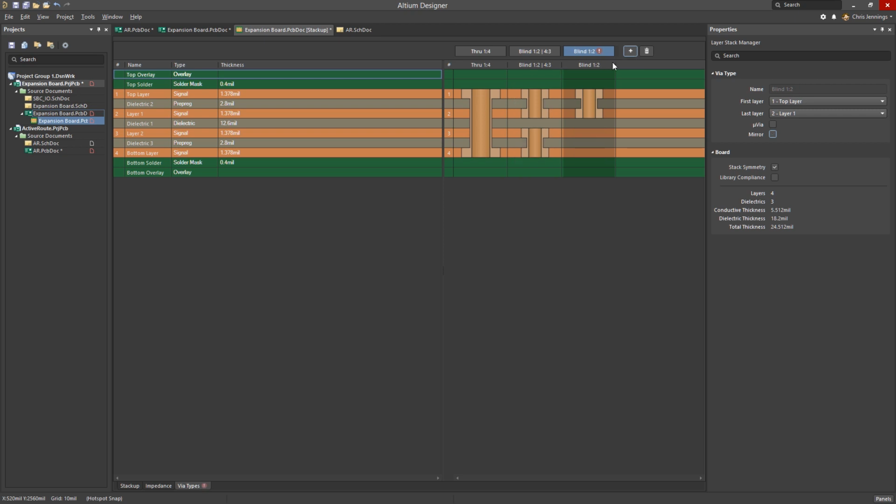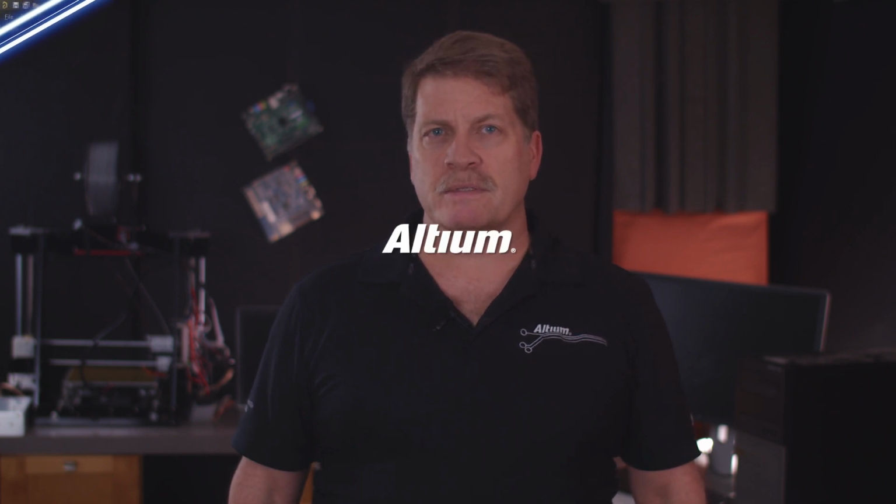If needed, Altium Designer supports micro vias. As you can see, the shape of the vias change. You can add other vias as needed, depending on the number of layers. Before we move on, the Feature drop-down menu provides different types of PCB projects, including printed electronics, rigid flex, and back drills. We'll explore some of these options in the next video. For now, let's talk about impedance.